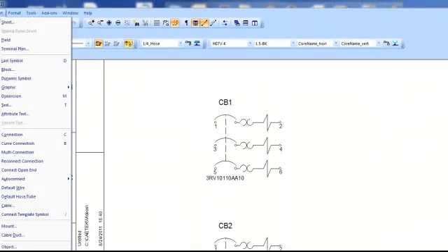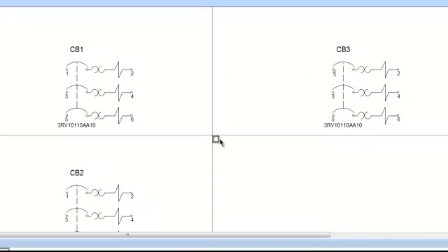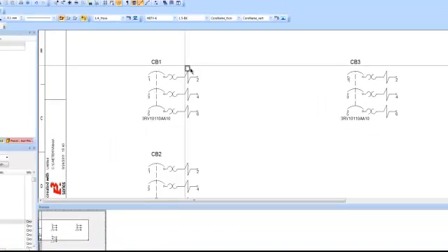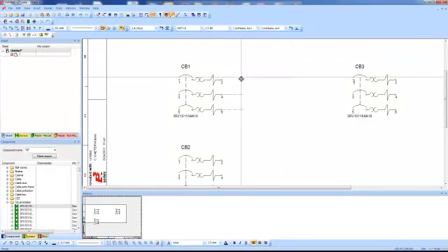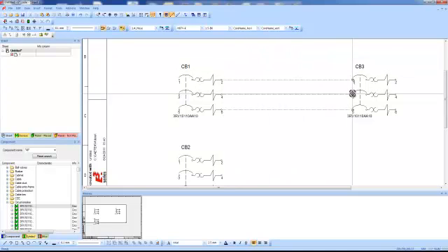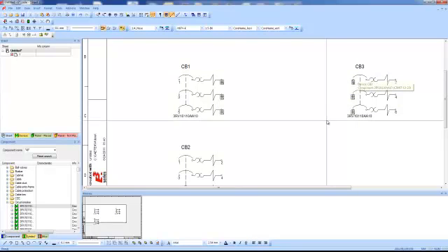And once again I'm going to select these and delete them. And I'm going to come back into insert, and there's a different one down here that's called multi-connection. Now what multi-connection does is pretty similar to the inside area, except here I'm going to select just these first 3 pins. Now you can see it allows me to draw them wherever I want to. So I could come across and automatically connect these up with a multi-connection, which is now 3 more signals will be generated, 9, 8, and 7. You can see that it actually flips those and builds them from the bottom to the top. So I'm going to delete that.